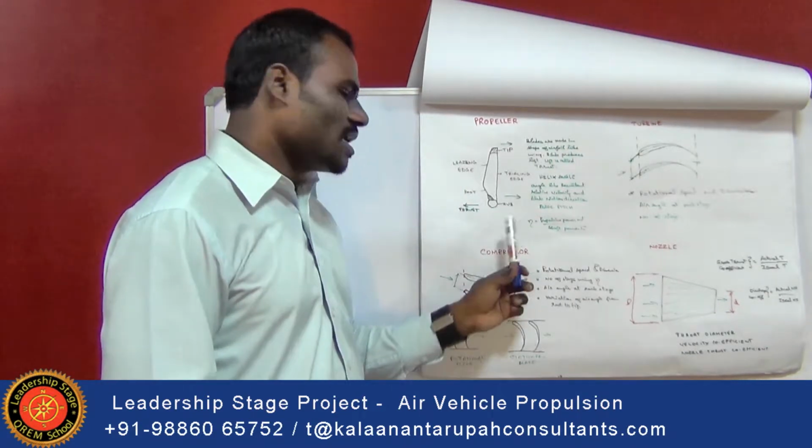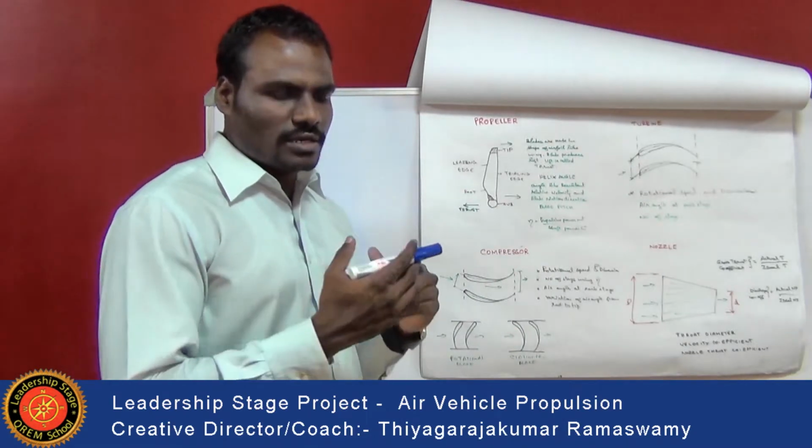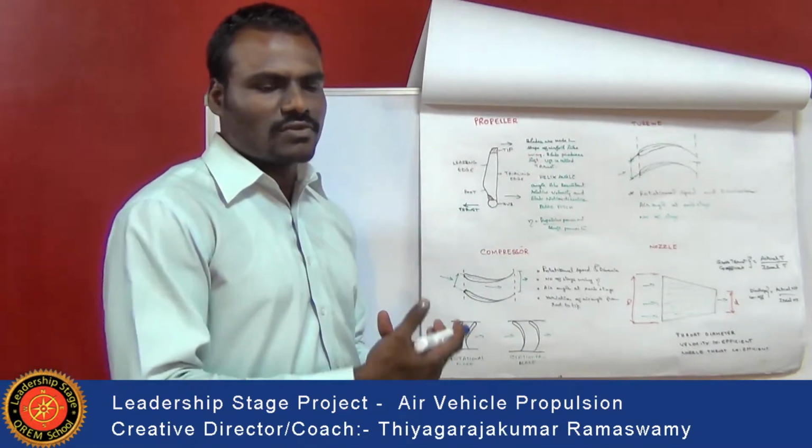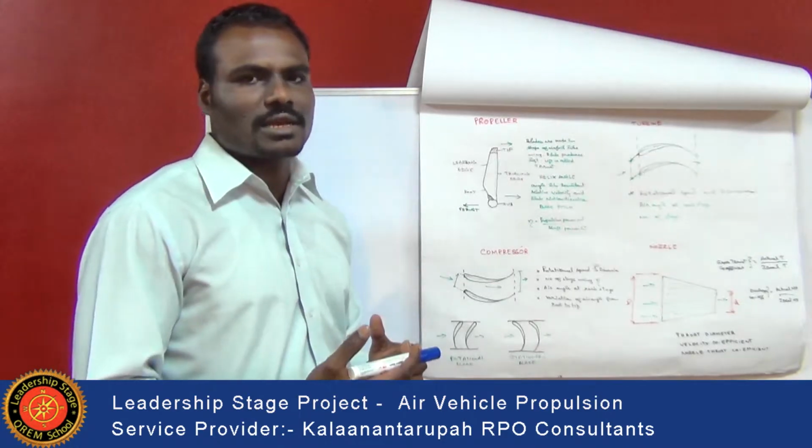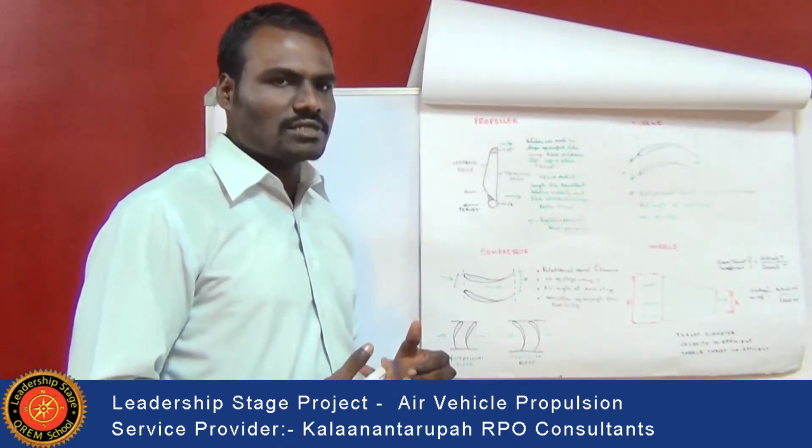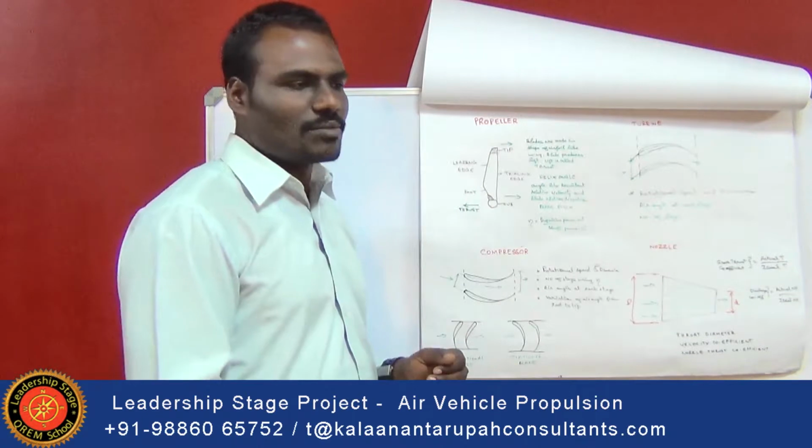Here the compressor plays the role of compressing the air which is flowing inside, increasing the pressure and the temperature of the air, which is then subjected to the combustion chamber.